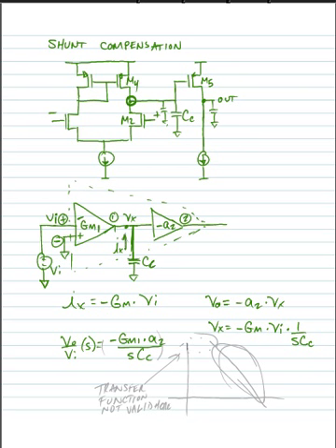So if we plot the transfer function here, we would see something like this. Now this transfer function is only valid at high frequency. This is not what the actual transfer function of the circuit looked like. This is with our simplification that we're looking at. But we're trying to find out what the higher frequency response of this circuit is. So here we have a one-pole roll-off that starts at infinity. So remember, the transfer function is not valid here. It's only valid in this high frequency region.